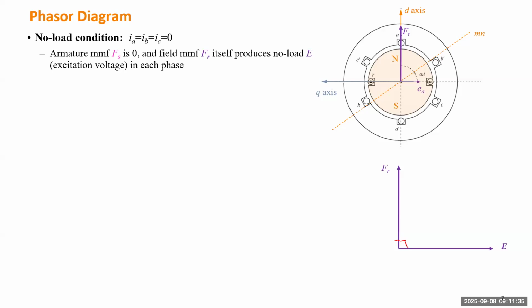Similar to the phasor diagram to study the voltage and current phasors, you can use any one to be a reference. So for this case, we can use this E as reference, which means even though this E is revolving together with Fr at a similar speed of 60 Hertz, we just assume the relative angle will be the same, 90 degrees for this case.